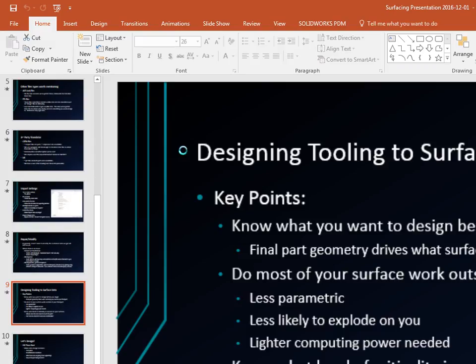Can you do an evaluate, to see how much interference there is or anything like that? There's no visual interference detection, if they're solids. With customers' parts, it's all surfaces, so then it doesn't matter. Yeah, that's true. What you can do is run a cut, and as you go through it, it'll show you where the surfaces differ. Like do a section, you're saying? Yeah, and if you look at the two surfaces, you can see the differences between the two. They'll be different colors.